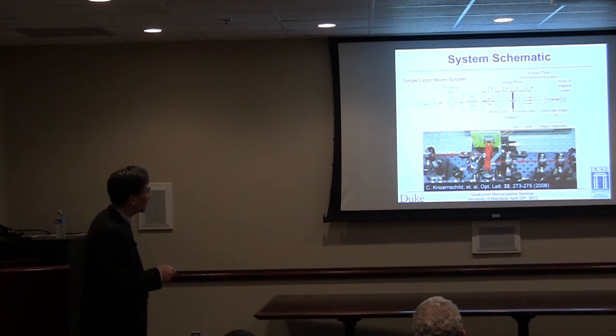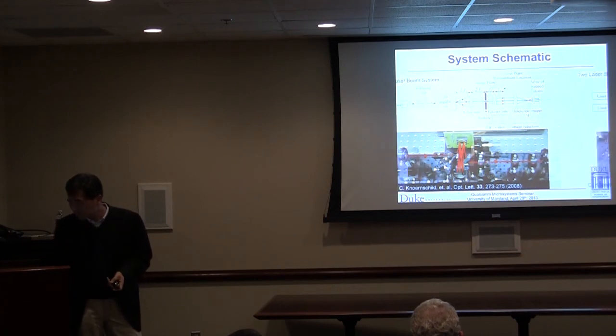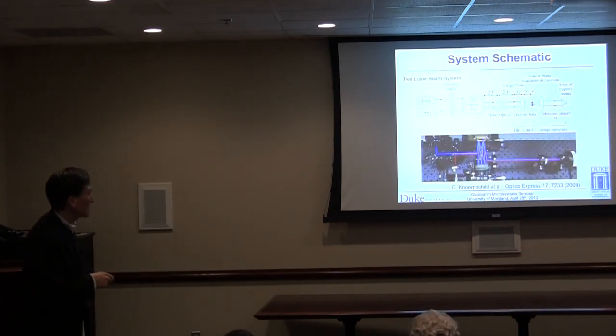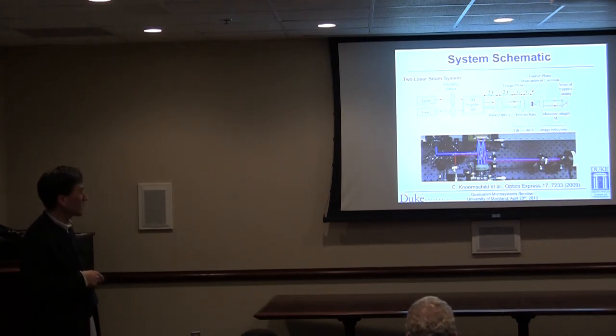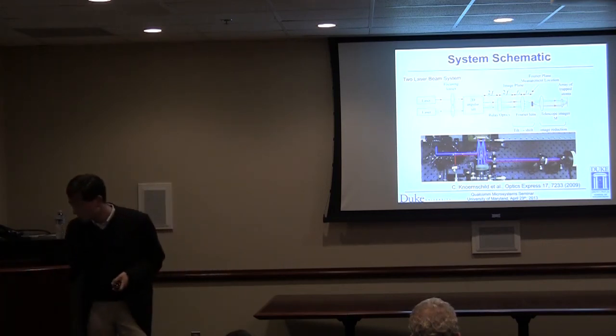This is a simple example of how a single beam coming in can bounce around. I have two mirrors, one tilting in the X direction, the other tilting in the Y direction. And the beam coming out can now steer in 2 dimensions. The beautiful thing about MEMS is I can use the same system, but instead of 2 mirrors, I can use 4 mirrors and steer 2 beams simultaneously. We could scale this up to large numbers of beams. We've constructed systems with up to 6 beams being independently steered.